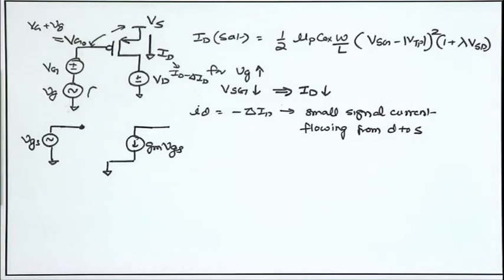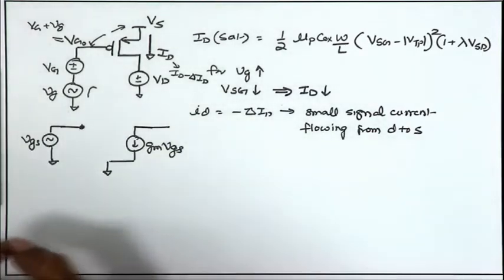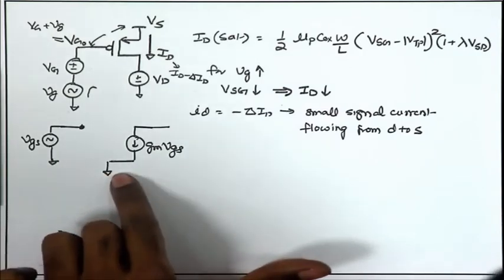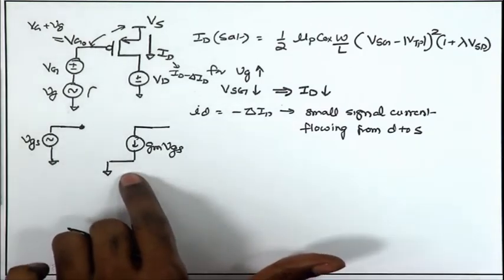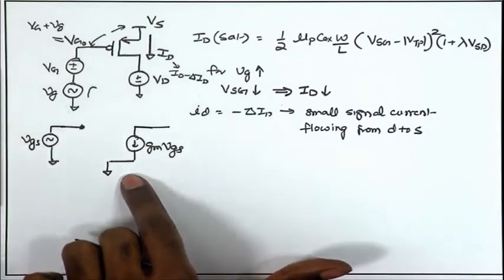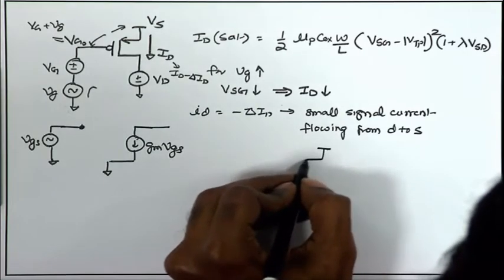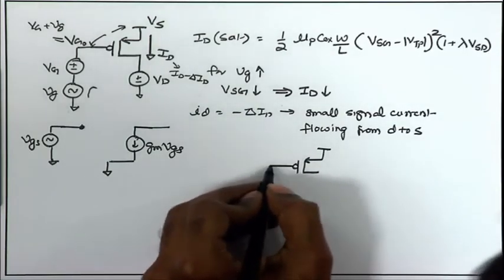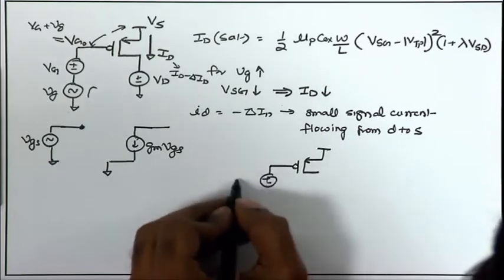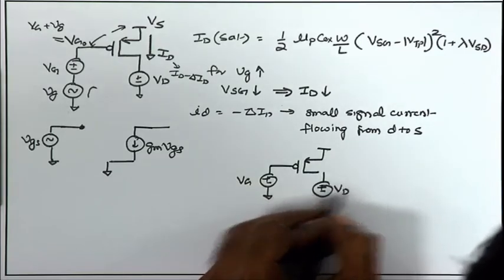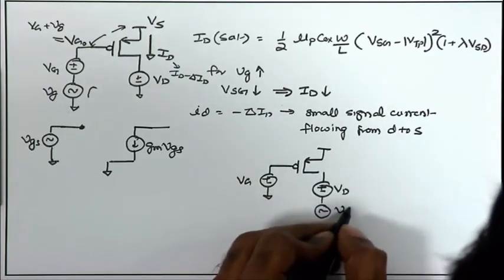And likewise, if I want to talk about Ro of the PMOS, it is supposed to be the small signal resistance of the PMOS. Of course, it has to be positive because we are talking about small signal resistance. So, we should not be so concerned about the polarity, but just confirm that we are getting consistent polarity according to this definition. If I keep my gate voltage at a fixed DC Vg, and on the drain voltage I have an AC signal, small Vd on top of the DC.